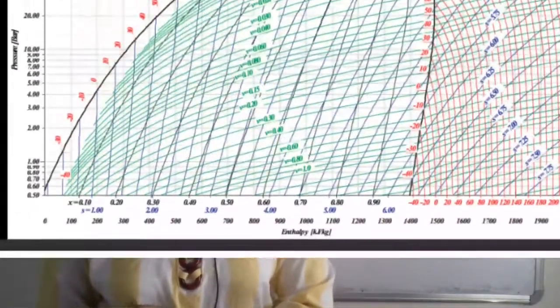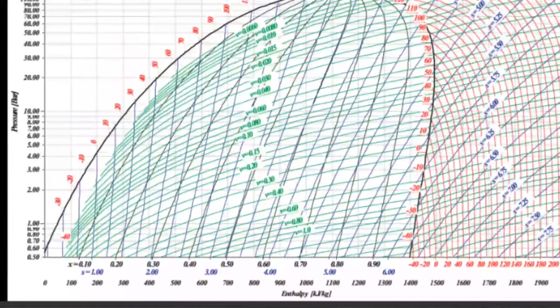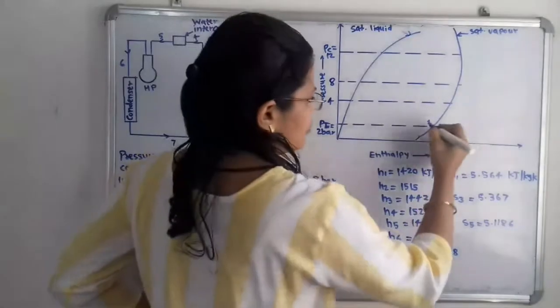So we have to find out what is the entropy at this point 1 in this pressure enthalpy diagram. So with the help of blue line, in the pressure enthalpy diagram, S is equal to that, particular entropy is given, that the line will be passing through this point 1. And that particular point, that is at constant entropy only, we have to take the compression process.